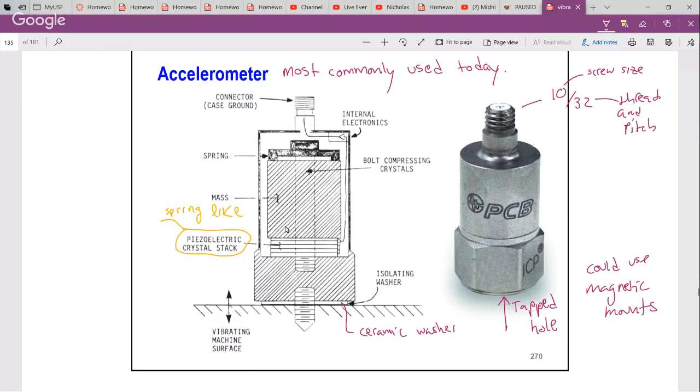All right, so the classic question that I like to ask is, what are three or four ways to mount an accelerometer? Stud mount, glue, and pop, if you like, wax. And people get creative. Screw, fastener. Those are probably good. Okay.